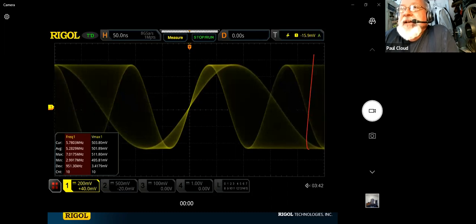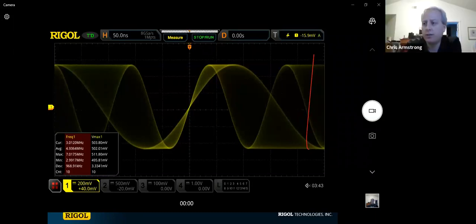I'm sure I can dig all this out of the specs online, but I'm interested in getting something like this to take on site to work on a repeater or something of that sort. What kind of power level am I going to get out of the tracking generator? Yeah, tracking generators are usually set from either -40 to 0 dBm. Okay. So you get up to a milliwatt out of that.